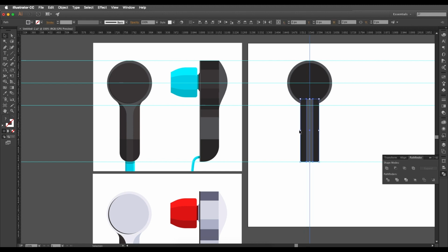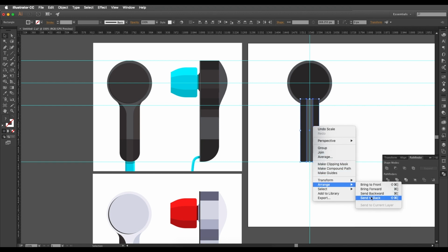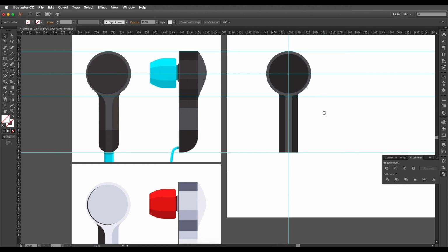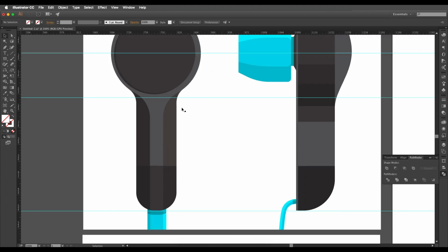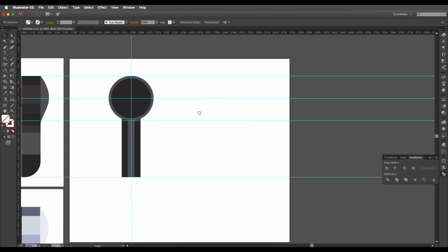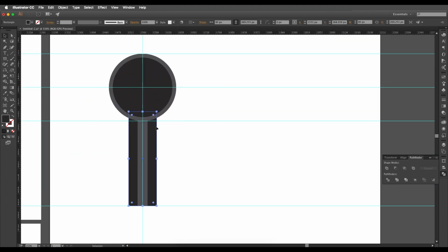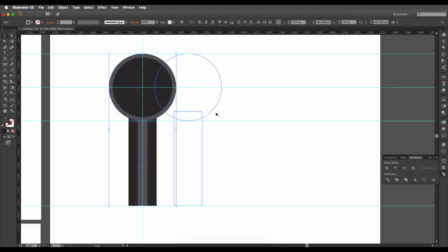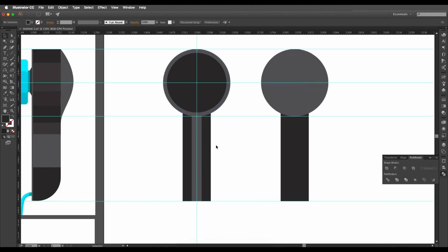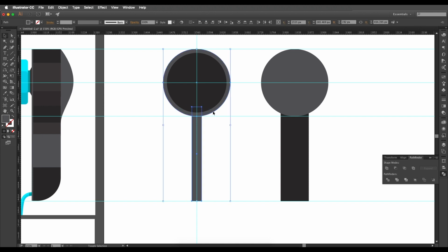Now I'll select both of these and deselect the ruler with a shift press, and I'll just arrange it to back. So send it to back, and here it is. Now to create this portion of the design, I'll just create one duplicate. Just select this circle and create another duplicate and drag it around here. So we got one, and I'll just delete this out. So we got one circle for the inner one, and one circle for the outer one.